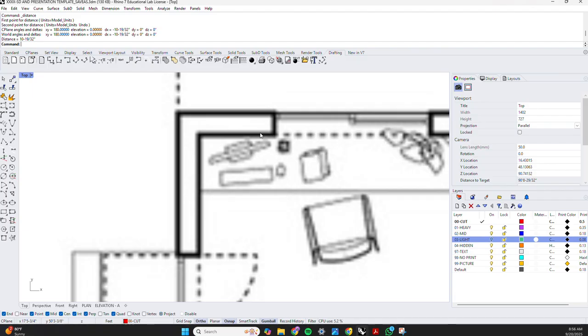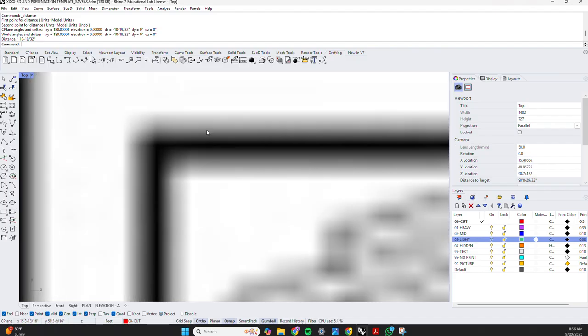When I first snapped the dimension here, it said like 9 something. When I did it here, it was 10 and 19/32. So when I draw this out, this wall should not be at 9 inches something and this wall at 10 and 19/32. These walls should be the same. And the fact that they're not the same, if we were to trace over this, is not a result of the reality of the project. It's a result of the imprecision of working with raster drawings.